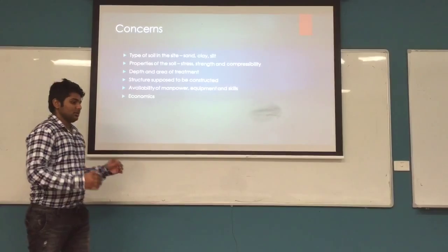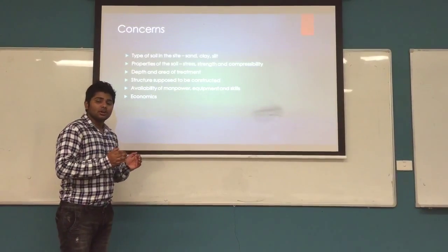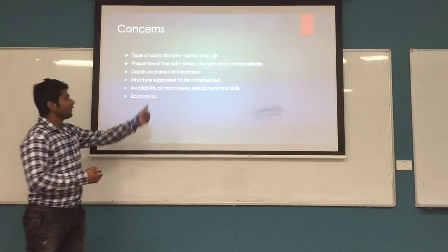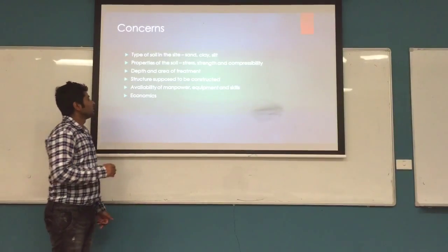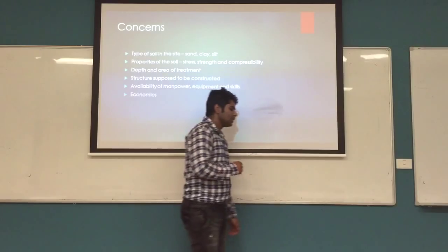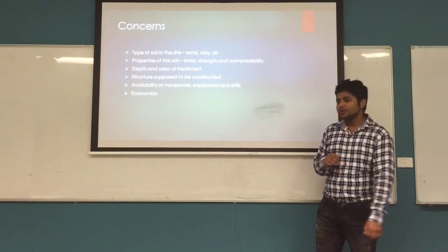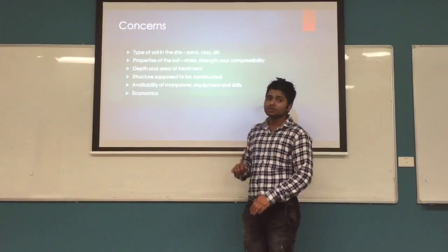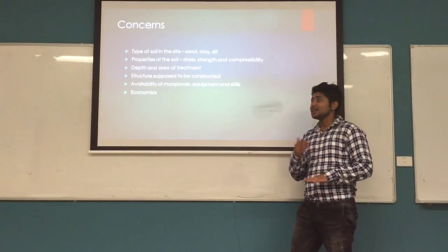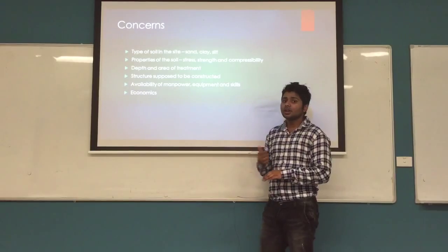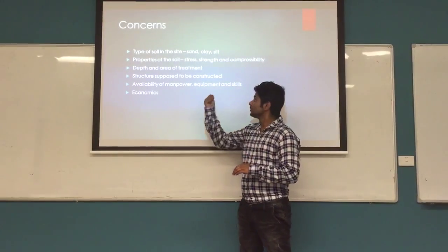We need to know the depth of the treatment where we are going to carry out the work, and the area of the treatment. Fourth one, the structure to be constructed. This is the major factor. We need to identify the structure above the soil, that is the load that the foundation will be carrying. The soil is to be treated according to the load to be carried.